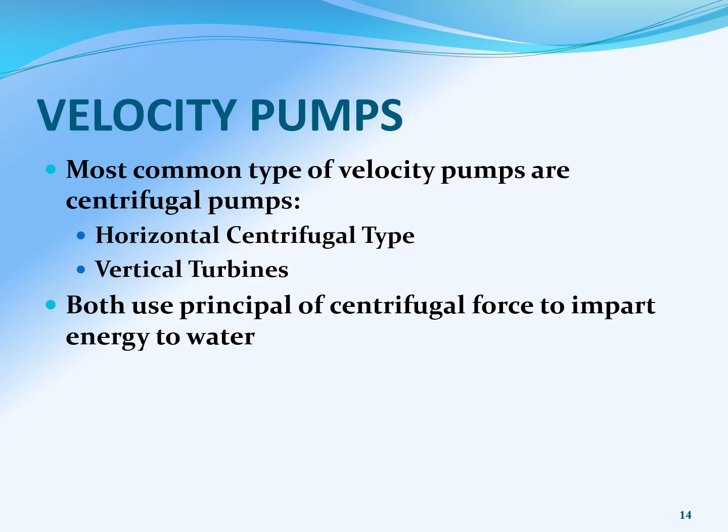So the most common type of velocity pumps are centrifugal. So you might see that question on an exam, but horizontal or vertical, right? So you can have those pumps oriented in different ways. It just depends on what you're trying to accomplish, what kind of space you're working with. But they both use the principle of centrifugal force to impart energy into water.